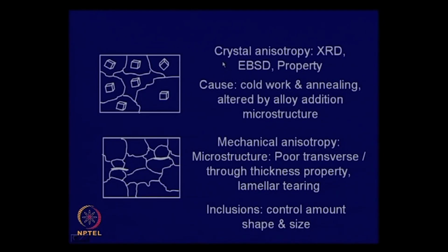And this can be determined. There are different techniques: X-ray diffraction technique, and electron backscatter diffraction pattern, which is a special attachment attached to the scanning electron microscope. By this also you can explore the extent of the crystal orientation or textures present in the material,